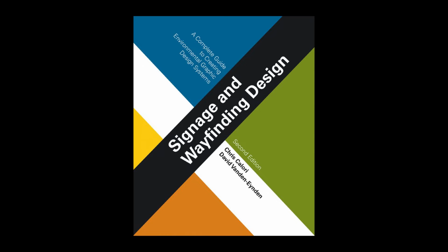The fixtures housing external lighting sources can be mounted below or above the sign and can vary from sleek and minimalist to highly noticeable, so the look of the lamp fixtures must always be considered in external sign illumination as much as their position to reduce glare and light spillage. One external sign illumination technique that doesn't require electrical power is specifically engineered reflective vinyl films that capture, intensify, and reflect light back from car headlights.